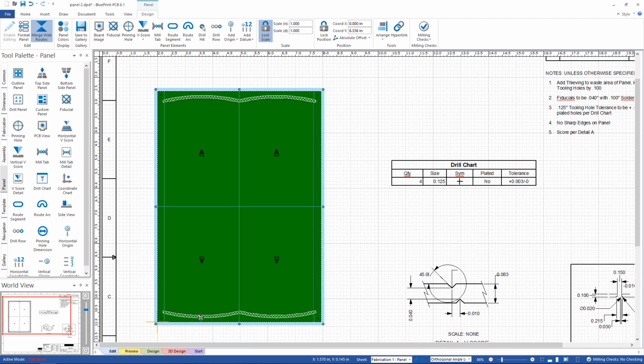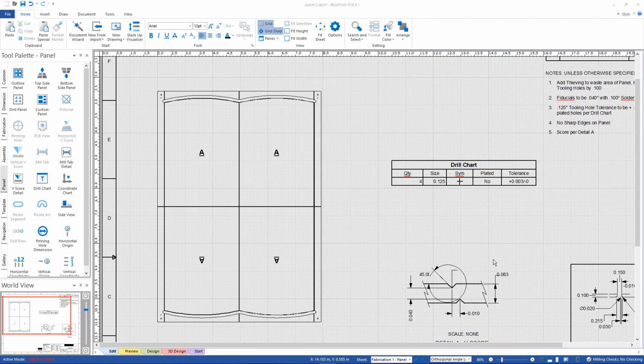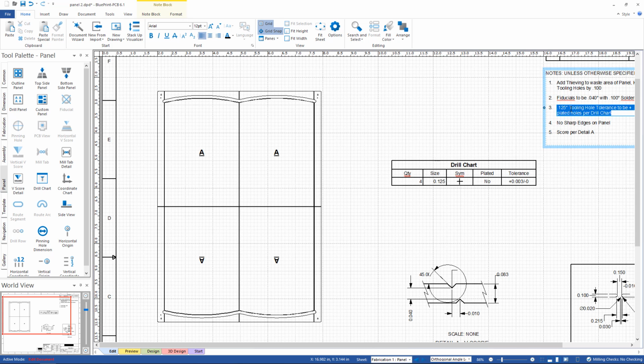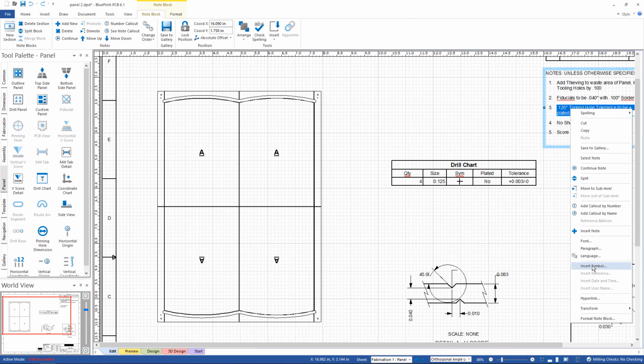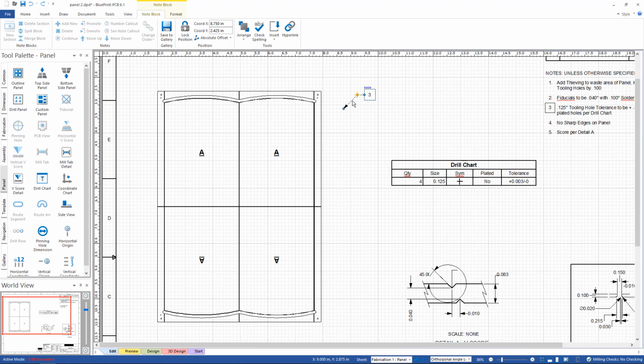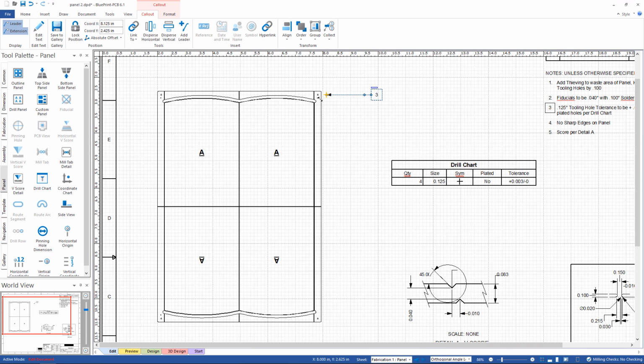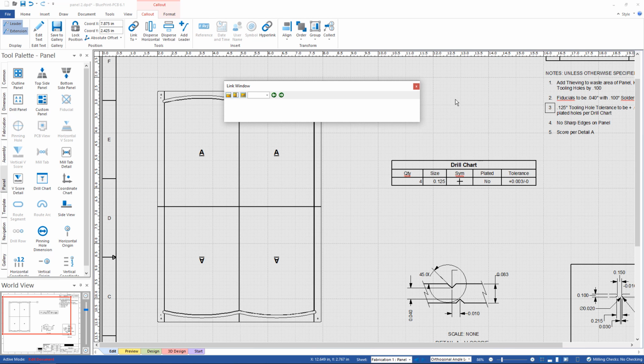Now I could put a mill tab in there as well if I wanted to and have a combination of all 3 methodologies. But here's just a quick way to do it without having to use mill tabs. And now I would just delete my mill tab detail again, add some callouts wherever I wanted to. It's just as easy to do here as it is elsewhere in the tool. You just basically point towards what you want this callout to snap to, and it is hyperlinked if you're doing electronic documentation.